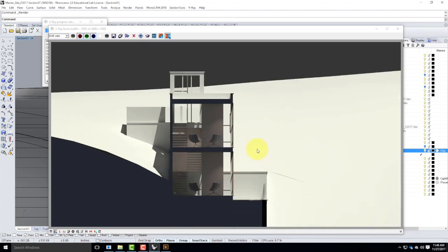Okay, so it went ahead and finished its render. The inside might be a little dark, but I'll post-process that in Photoshop just a little bit. Couple things to keep in mind. Because we did the building the way it was, the full shadow of the building is cast, which is what we want. Furthermore, these lights and little reflections on the wall are accurate as if the whole building were there. So that's one of the key things to keep in mind in this, and it does make a big difference.